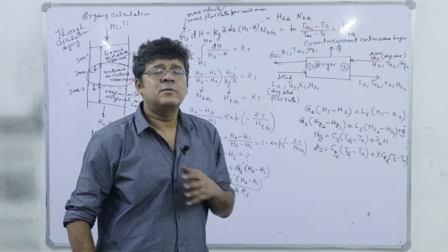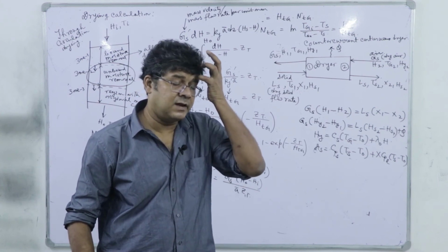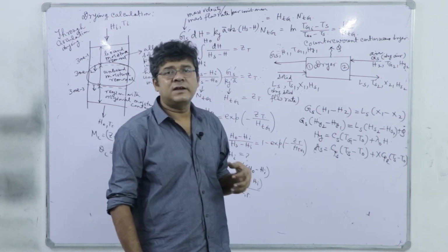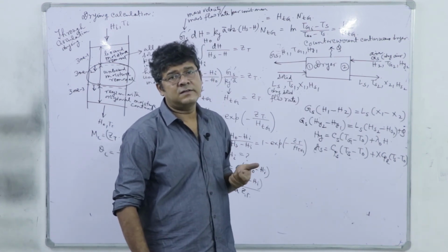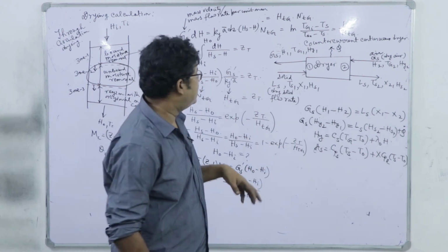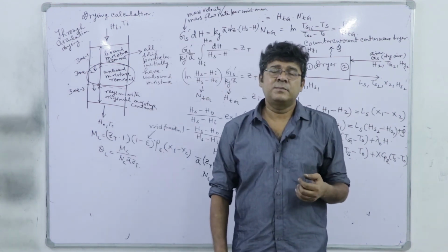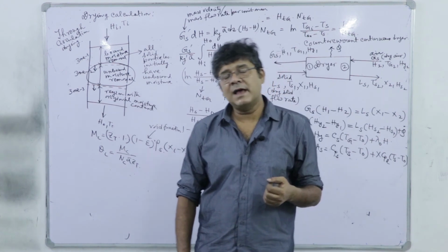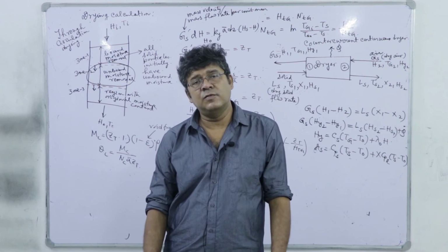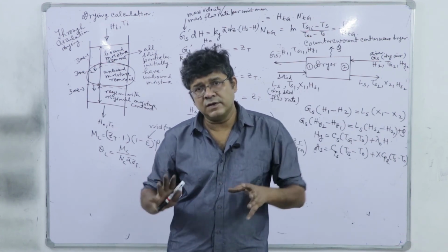The point there was how to calculate the outlet gas temperature in terms of this inlet gas temperature and solid surface temperature. And from there we have calculated basically the NC, the constant rate of drying, and theta C also, right. So next we have considered this through circulation drying in this packed bed mode, that's also a batch, but we have considered only the unbound moisture removal over this constant rate period.